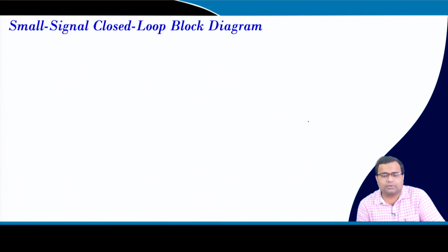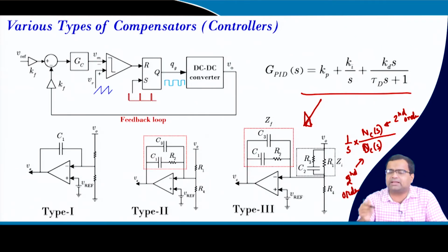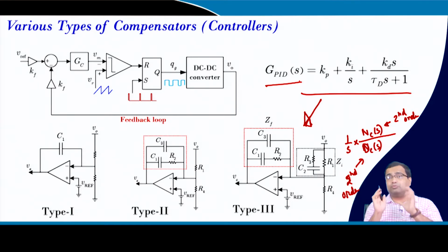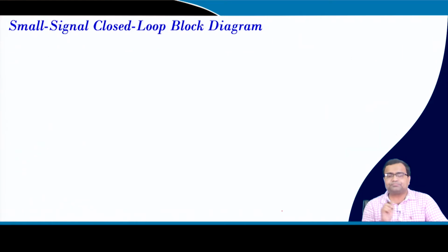And also it will show that the PID controller is of course not sufficient for a boost converter because there is a right half plane zero. So, you need to anticipate that effect using a type 3 compensator. Generally that is why the type 3 compensator is a very popular choice under voltage mode control.